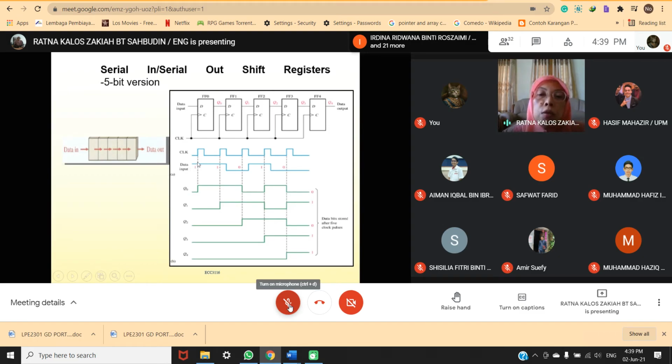So now look at this clock, and Q1. Q1 is low here until this clock here, this is high, so you have high. At this clock, still high, so high. At this clock, this is low, so low. Now Q2 becomes the input for flip-flop number 3.